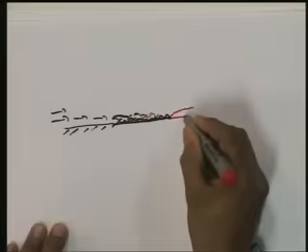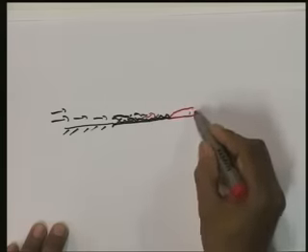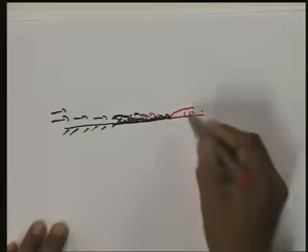And then another important factor I have listed here is suction of the boundary layer. In most cases a boundary layer will be formed. Boundary layer formation can take place when the free stream flow is coming, and if there is suction for this boundary layer, then also the flow can change from laminar to turbulent.